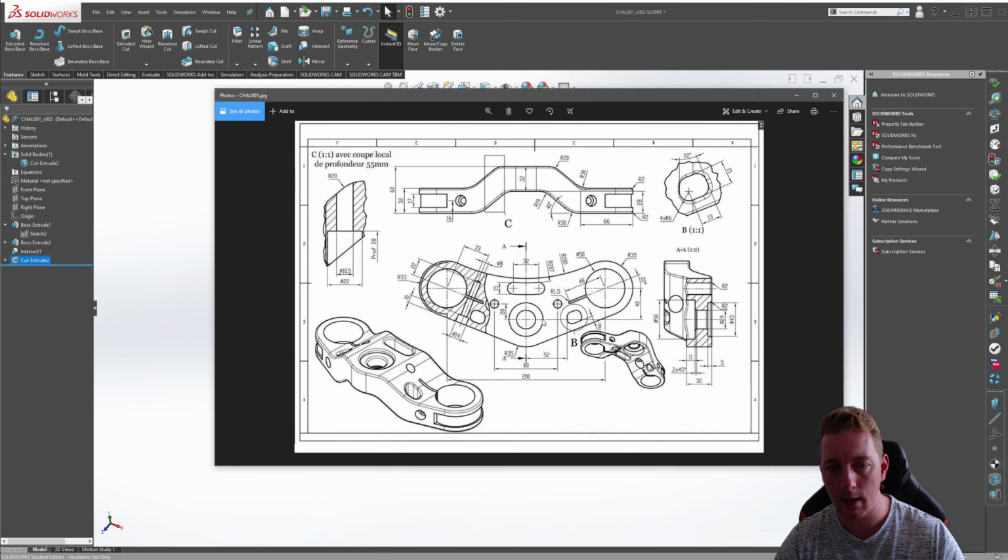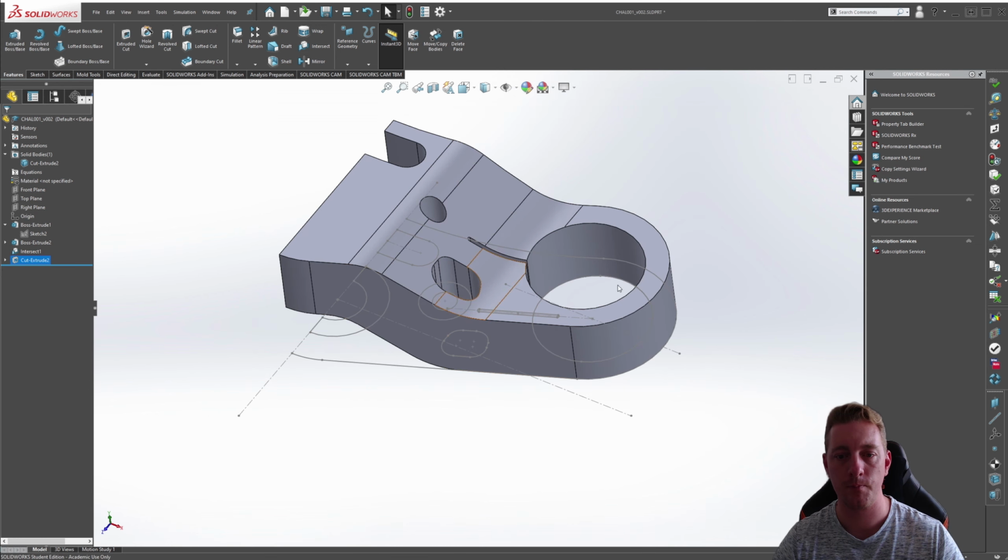So with the other holes that cut through, unlike these ones, the slot, this circle, and this, they all just punch straight through. But then when you start looking at the cross section for these holes here, it does have a larger diameter that sort of goes to a certain height, which is 28 from the base. You also have some other holes like this center one. You can see a side profile here. It sort of steps around a little bit differently. So going back to our original drawing, we can do this hole here. So we're going to make another cut.